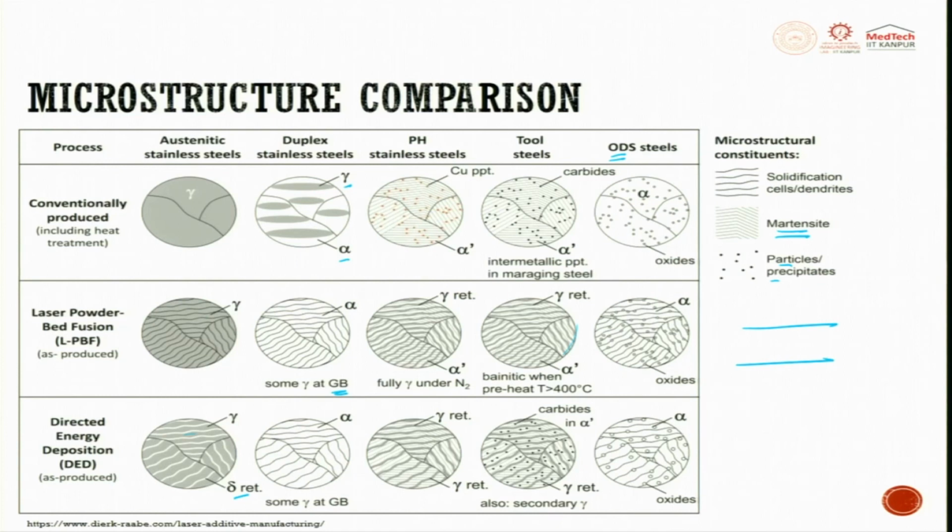And here in laser powder bed fusion, you can also have selective reinforcement. For example, in a powder bed in one layer, suppose let us assume these are the points or these are the tracks where you will try to have maximum wear resistance compared to the rest of the part. So, you can play with the hatch pattern, you can play with the laser movement, you can play with densification and make these two lines or two small thickness lines where there is very high wear resistance, which is not possible in conventional techniques.